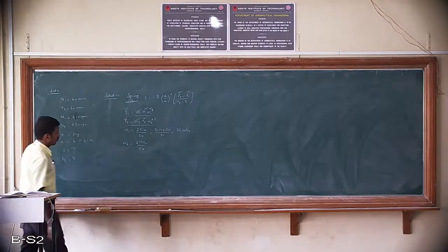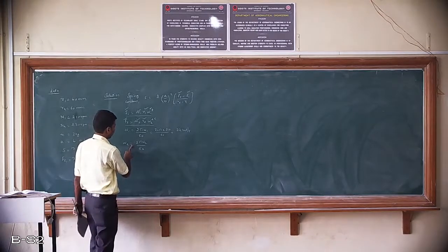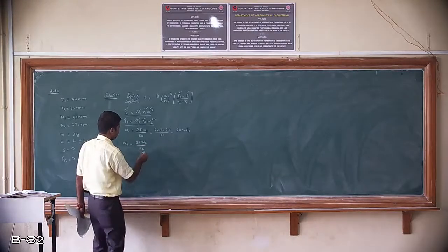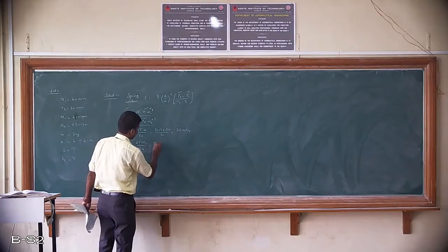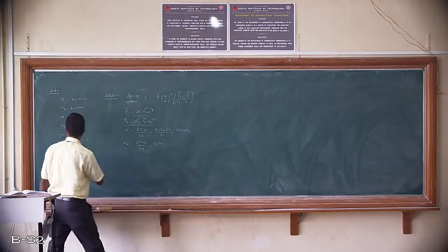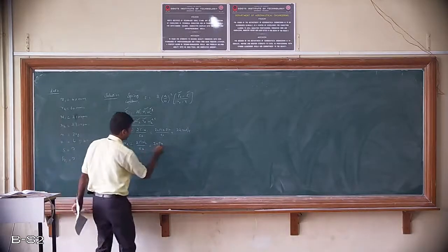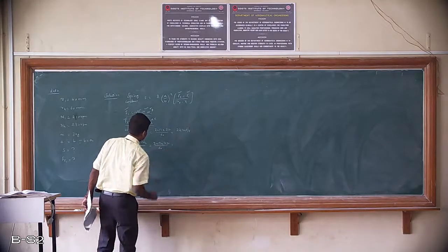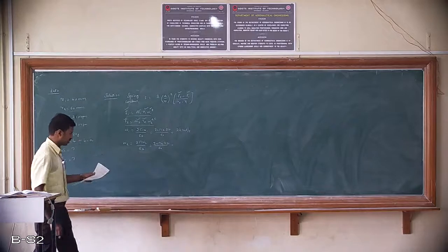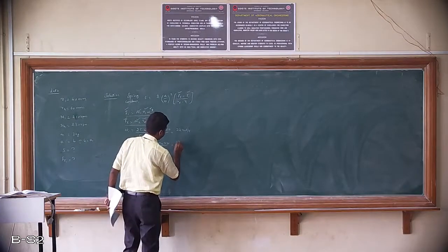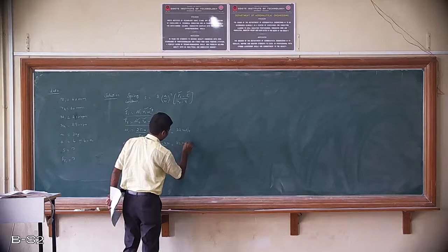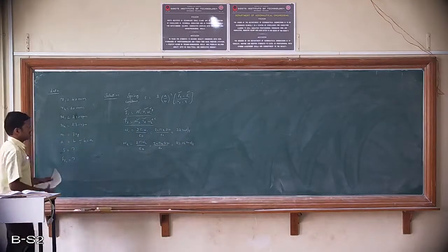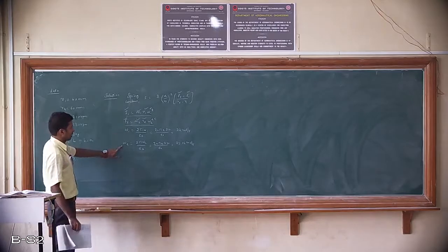Next, go for omega 2. The equation to get the value of omega 2 is 2 pi n2 divided by 60. So it is 2 into pi into n2, which is how much? 230 divided by 60. So we get the value of omega 2 as 23.04 radian per second.